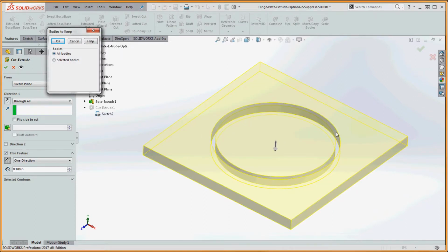And now it's going to give us an option. So everything is yellow. Everything's giving us highlight. We can select our bodies. So what do we mean by bodies? These are solid bodies. Solid bodies are like parts within parts. They're kind of detached from other parts of the model. A way you can use these different bodies within a part is to put that into an assembly, create different configurations of those different solid bodies, and actually have one part with a number of different solid bodies in it that can be imported into an assembly. Now it looks like you're importing in a bunch of parts, but that's kind of complicated and pretty winded right now, so we're going to ignore that for now. Just know that that option is there. And for a solid body, it's just like two separate parts within a part. It's one way to think about it.